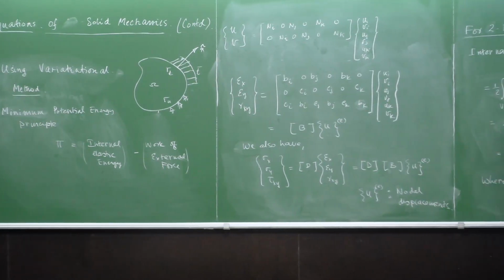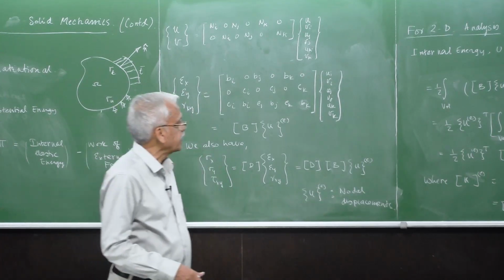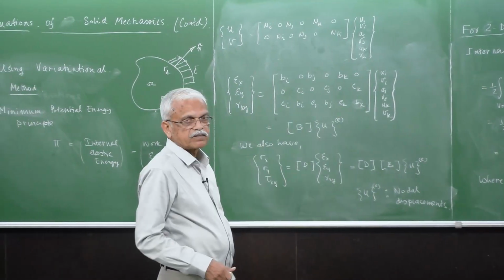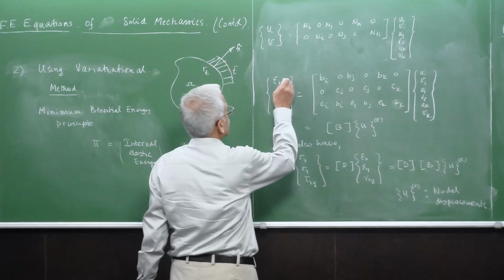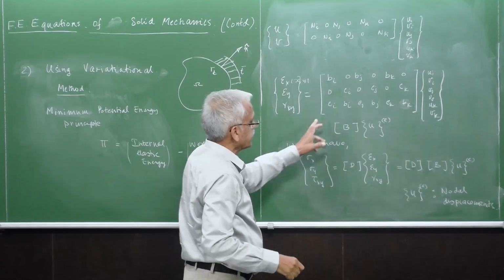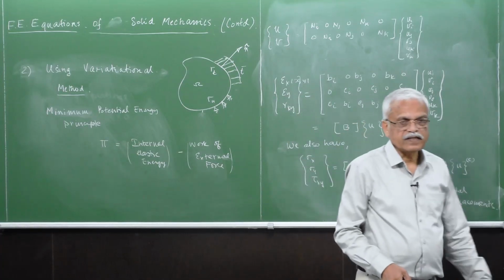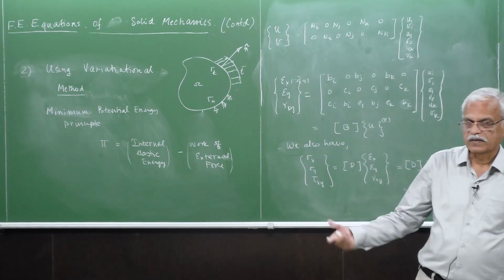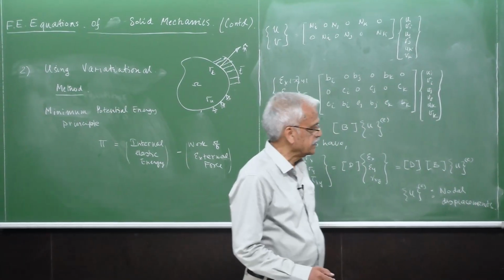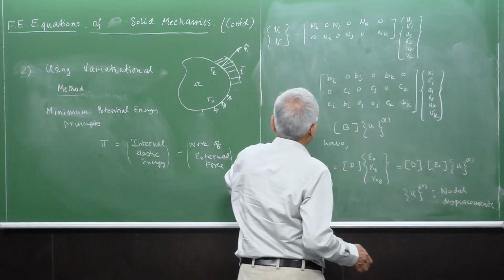So this is another important fact here, that this B being constant means that, whatever be this nodal displacement, the strains anywhere within the element, right? These are all supposed to be a function of x, y, all of them. But here for this three-noded triangle, this turns out to be constant, which means that the strain anywhere within the element is constant. It's all the same. So that is why this element is sometimes called the CST. So this element is called the constant strain triangle.